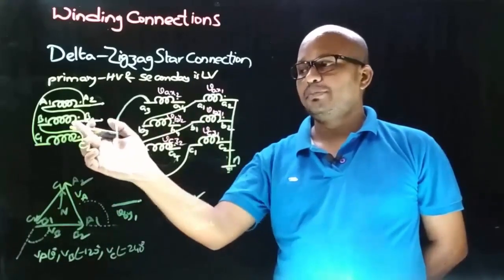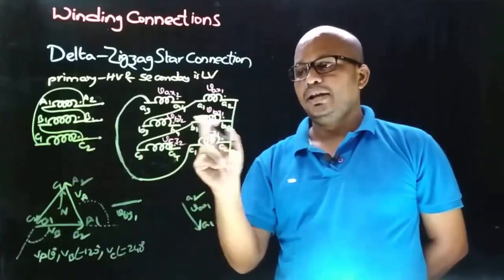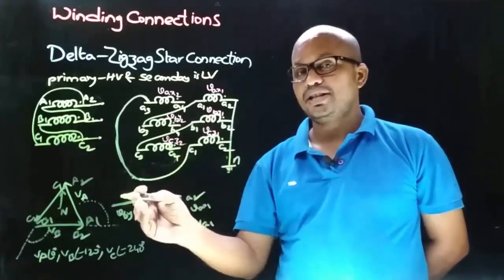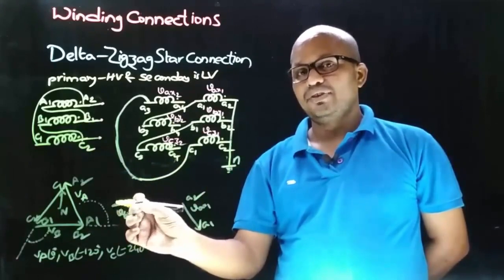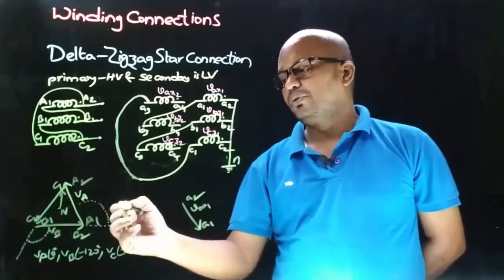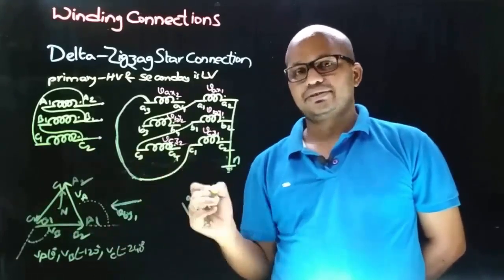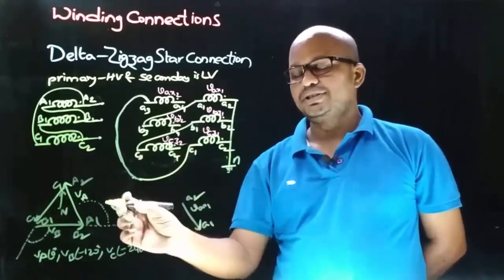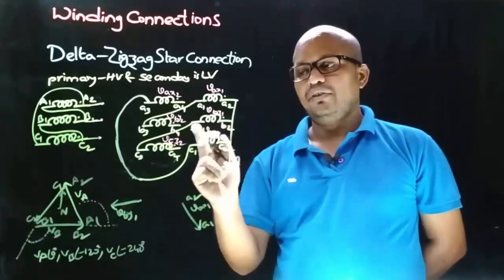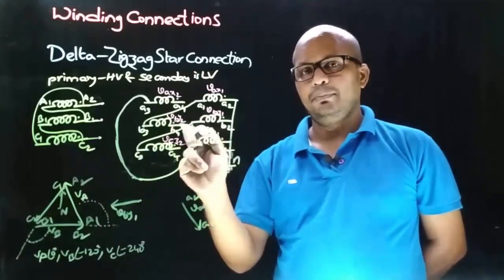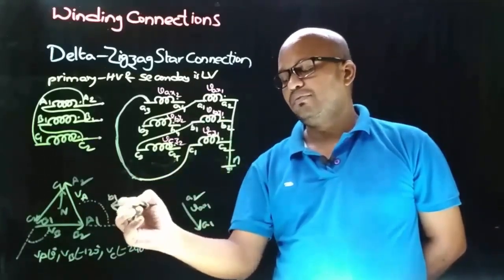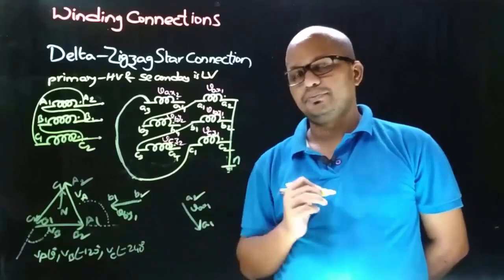And observe that on the primary side the connection is taken from dotted, and on the secondary side the connection is taken from non-dotted, means the direction of the secondary side VB Y1 phasor is opposite to the primary side VB phasor. Therefore the direction is like this. Now we need to decide these phasor terminals, B1 and B2. As the connection is taken from non-dotted, that is B1, therefore the arrow will point towards B1 and the other will be B2.